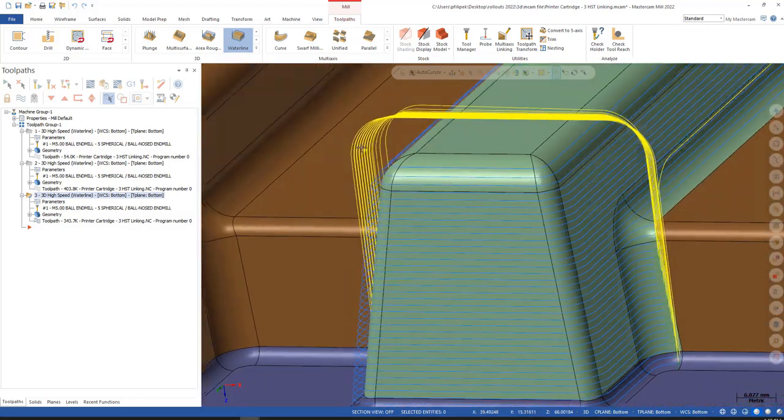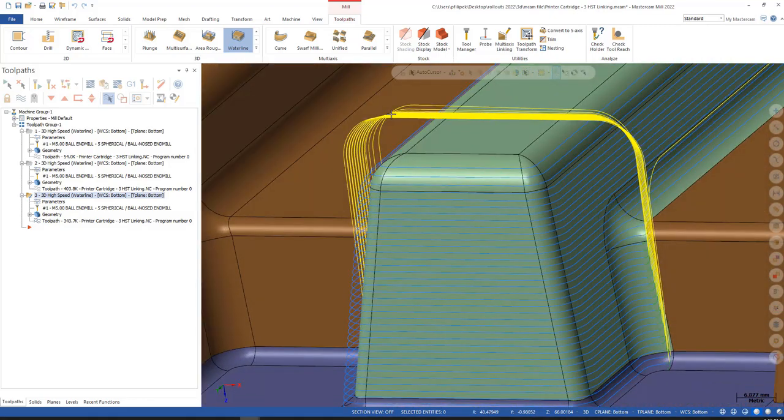Now you've got a nice radius on top. Your machine is probably going to like that a lot better. You're not coming to a square point and then taking a 90-degree left or right in this case. So that is a handy button if you are having issues with those transition moves, where your machine gets a little jerky, or it just doesn't like it.